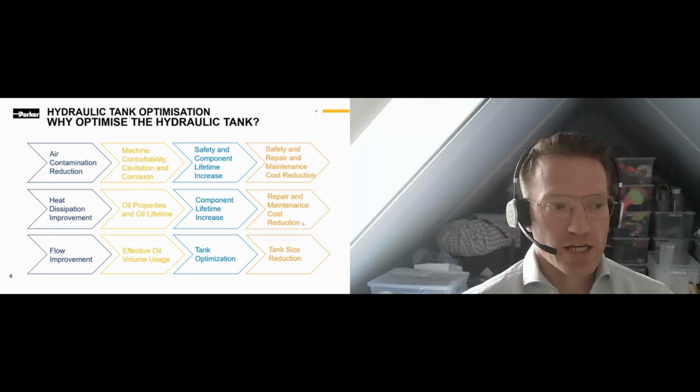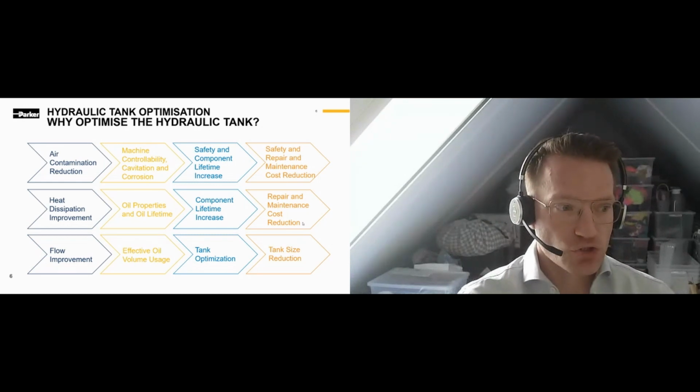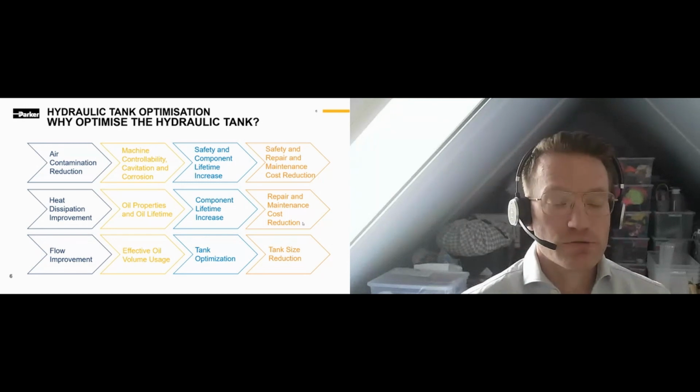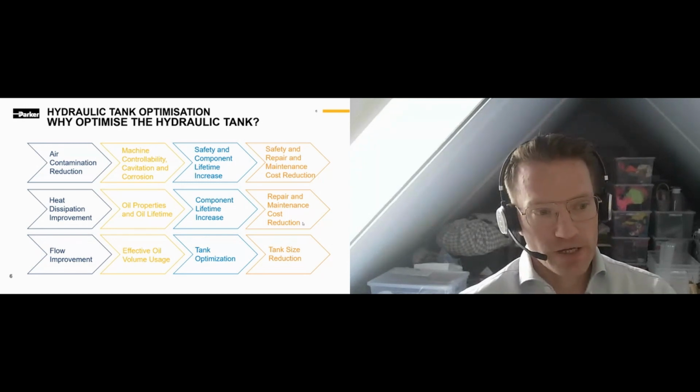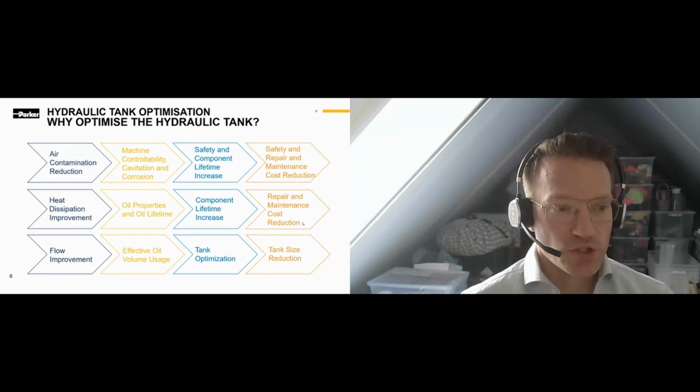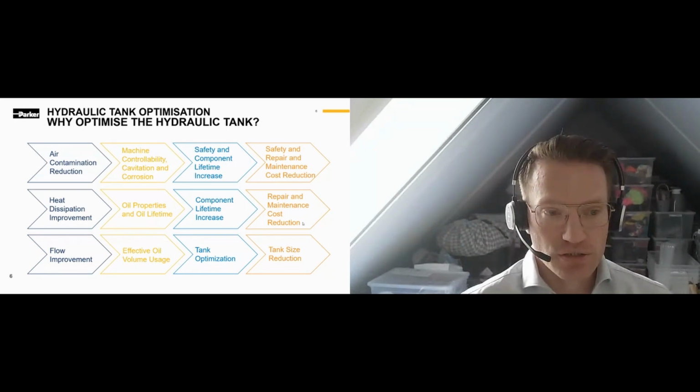But the most important aspect of tank optimization is controlling and improving the flow distribution throughout the tank. By improving the flow distribution, we can utilize the full tank volume, and that's basically what we call tank optimization. And that will enable us to reduce your tank size.